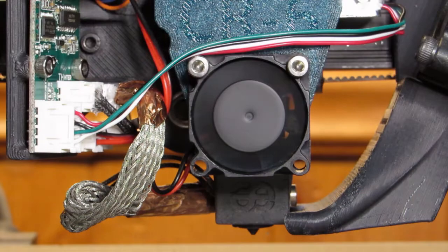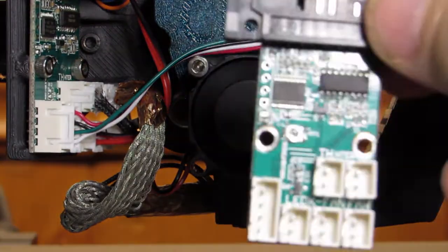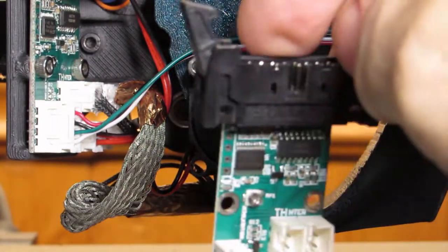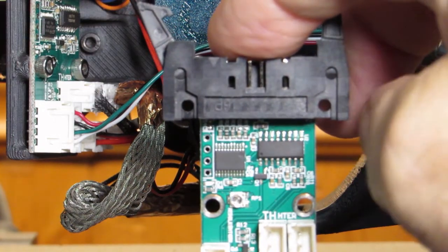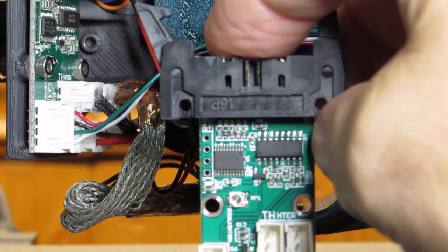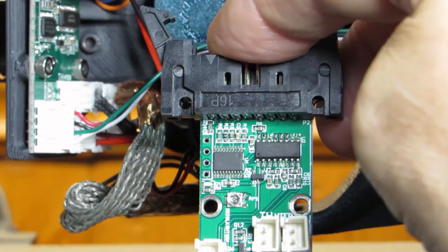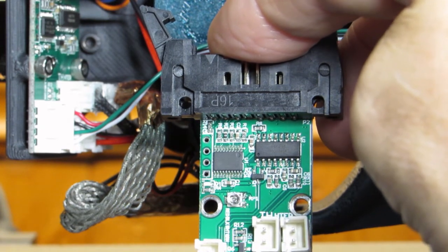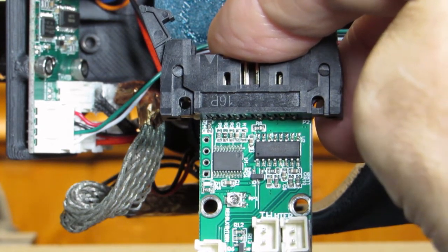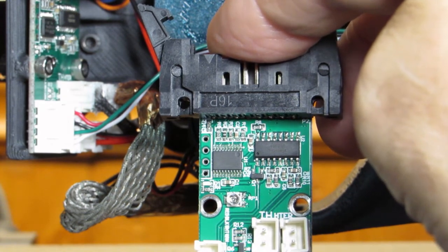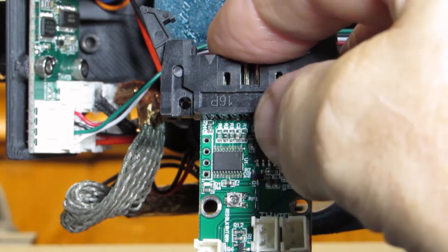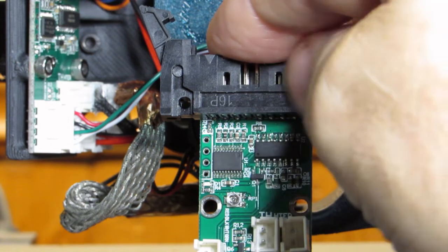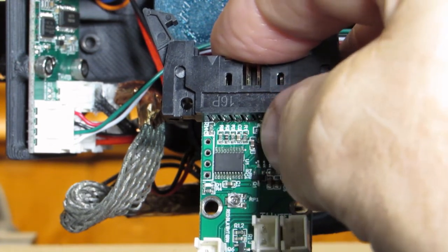And on the daughter board, there's some firmware, the design of which Creality has not released, so we have to guess. But logically, we suspect the larger of the two chips is like a digital scale. It looks at that resistance and it's programmed to translate the readings into how hard the nozzle is pressed into an obstacle. If it's floating free, it's not pressed in. If it's pushed up against the bed, it's definitely pressed in. Has it been pressed in hard enough to declare that we're actually pushing through any molten filament that might be residing on the nozzle and pressing against the bed?